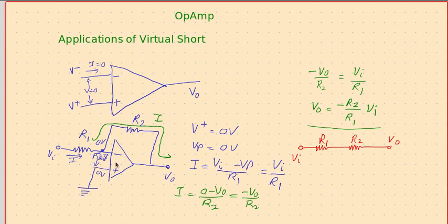Then because of the operational amplifier, we have been seeing that this point voltage is 0. So that means it is equivalent to connecting this point to ground. If you connect this point to ground, what would happen is this current I whatever we have found here will just sink into the ground. Then what should come here? Nothing. There is no further flow of this current as we thought here.